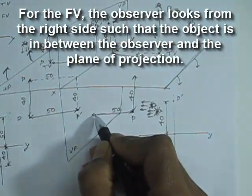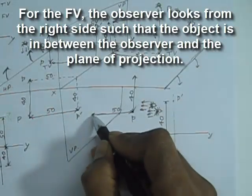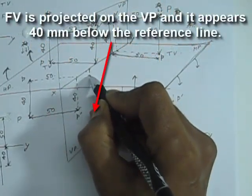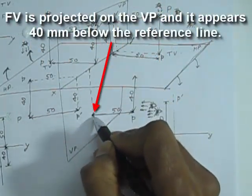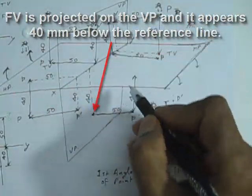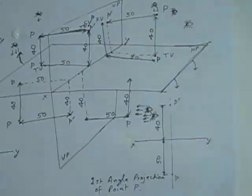For the front view, the observer is looking from the right side and the object is in between the plane of projection and the observer. So the front view is projected on the vertical plane and the front view will be 40 mm below the reference line.